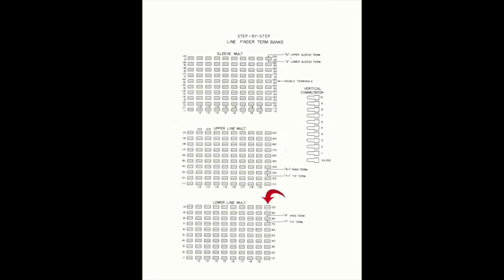However, if line circuit 00 connects to line finder number 1 on a dial tone request, it takes about a full second to get dial tone, because the line finder shaft and wipers have to step vertically 10 steps and rotate horizontally 10 steps to make the connection. However, this inequity is much reduced when all the line finders in the group are considered together as a single serving unit. We'll see how this is accomplished shortly.